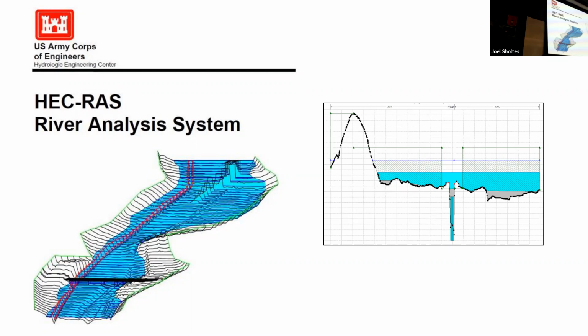It's evolved. What we're seeing here is a series of cross sections that represent the river. So here's one of those cross sections. And this is just something that you might survey. When we look at LiDAR, and if you've taken my GIS class, you've dealt with that data, that's going to scan anything above the water, but typically you're not going to get any information from below. And so someone's going to have to get out there in the river and survey that either directly or from a boat. So it's often very involved to get the information that you need for a river model, a RAS model.